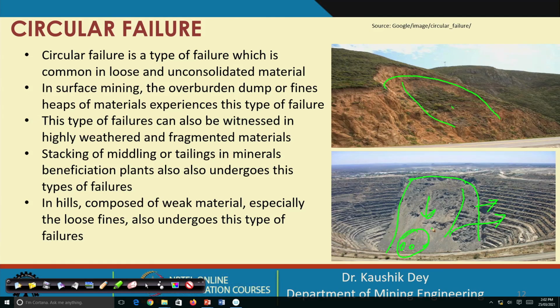inside, that is, prediction is very difficult, and that is why this failure occurs if sufficient analysis is not carried out beforehand. This cannot be controlled otherwise. So, that is why circular failure analysis is very important. Nowadays, slope stability radars are there to analyze the movement. Apart from that, surveying techniques are there. Formation of cracks on the surface is also monitored. So, all these technologies are adopted, but circular failure is a huge devastating failure. In general, the consequences are considered to be very high.